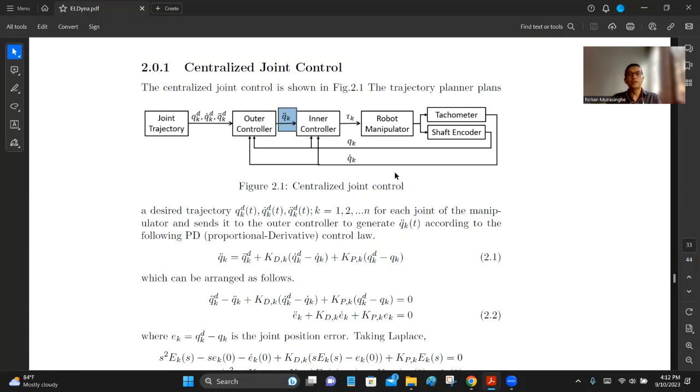And then these torques are to be realized in the manipulator, right? And you actually execute this, realize these angular accelerations, and therefore corresponding velocity, acceleration, position, and you drive the entire manipulator as close as possible to the joint configuration, right? Q dot, Q double dot for all of the joints.